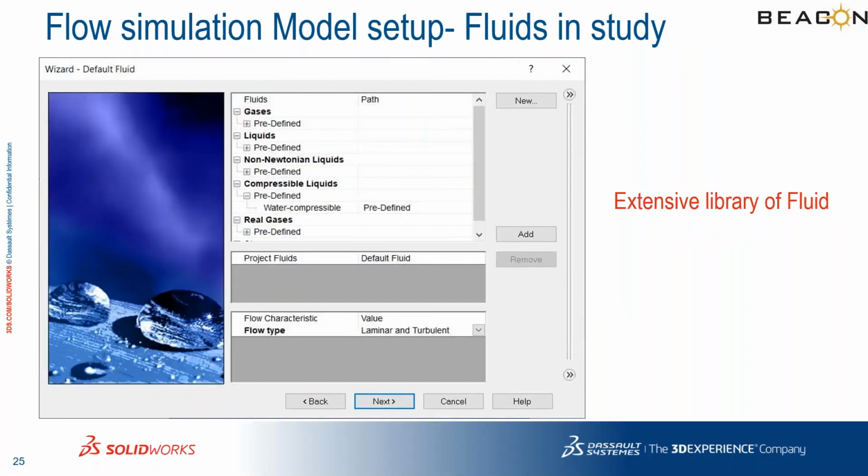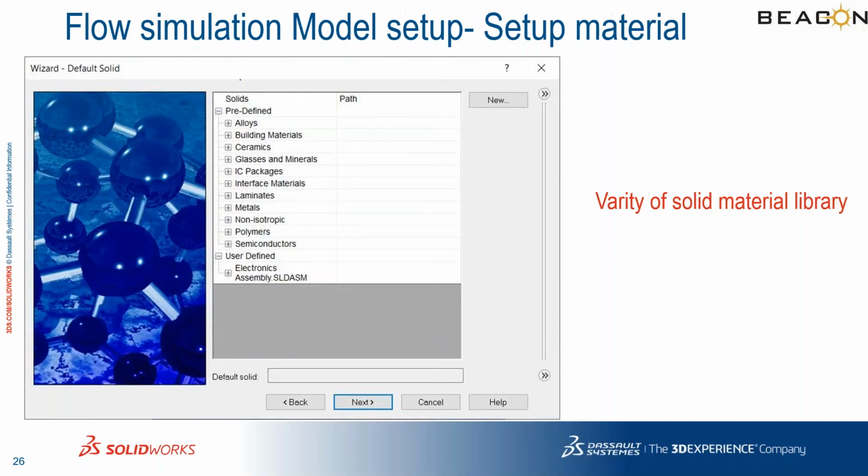Not only that, if we just move on, we can define the fluids that are part of the study. We have a very extensive fluid library. We just have to click over here and specify any fluid characteristics. If you want to add any fluids also, we can add them using this interface. And afterwards, we have to specify what are the solid materials involved in this analysis.